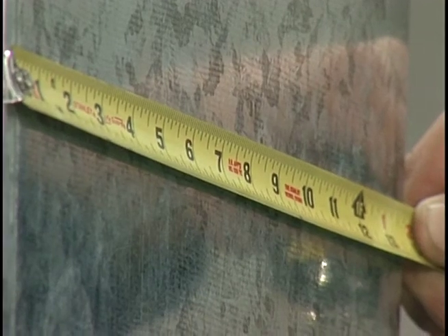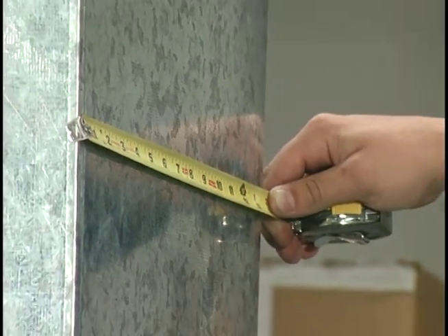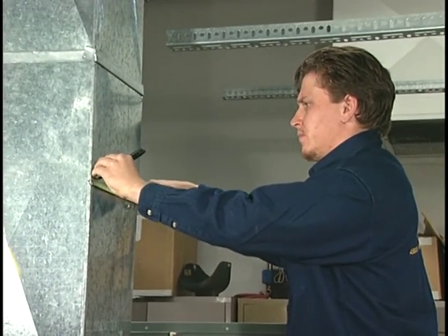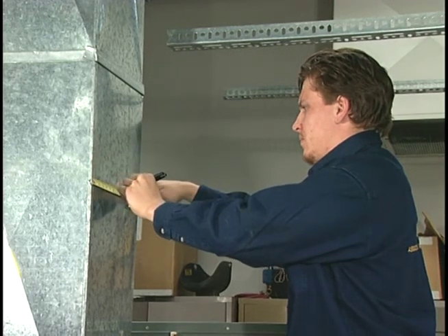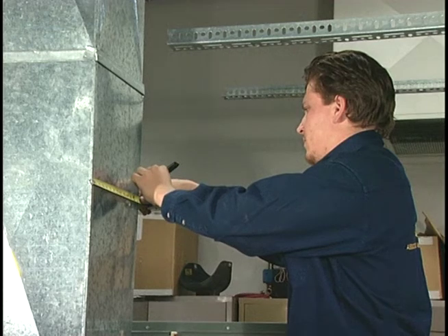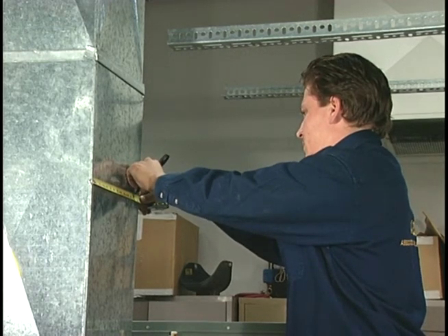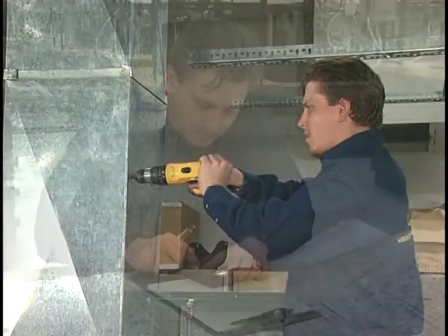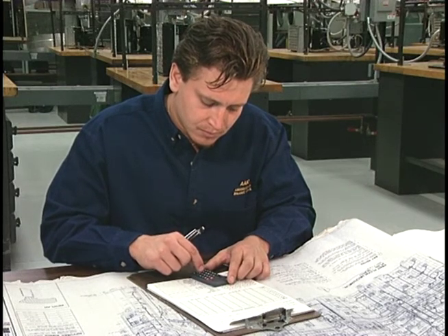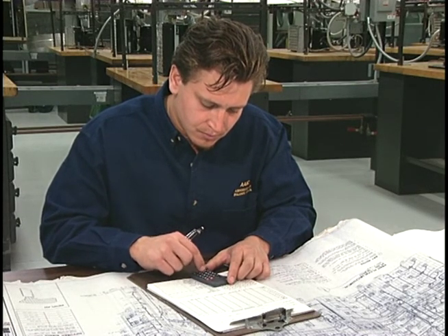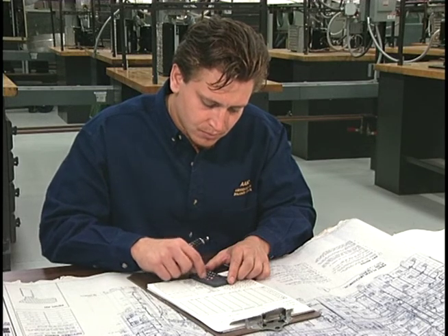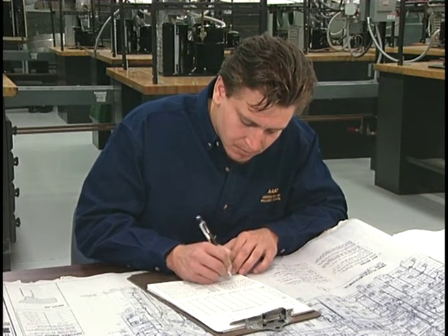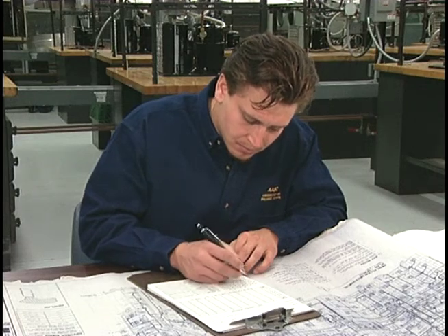In order to make a pitot tube traverse, the technician first determines the number and spacing of the holes in the duct and the markings on the pitot tube. The number of holes drilled, their distance apart, and the number of pitot tube points are based on the criteria for a rectangular duct, that a minimum of 16 and a maximum of 64 readings will be taken at centers of equal areas. To determine the number of holes and distances to be drilled, the technician arbitrarily picks a number and divides it into the length of the side where the holes will be drilled. If the result of that division is greater than 6 inches, the technician will continue with larger numbers until the result is 6 inches or less.